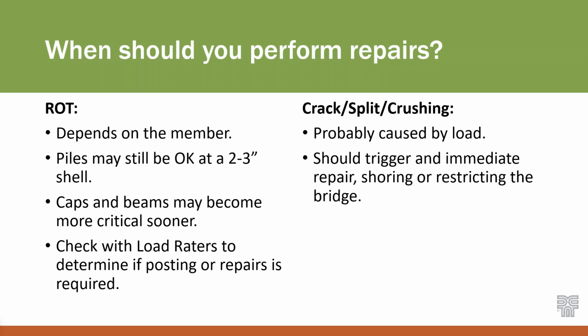So that should be a pretty good indication to us that if we're getting damage from load, we should be looking at what caused it, and it should probably trigger an immediate repair, shoring, or a restriction. I would again reach out to load raters or whatever maintenance folks you have on staff and have them do an evaluation if you're not sure of what should be done.